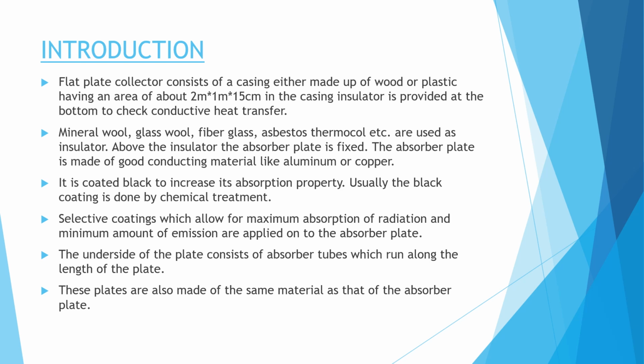Introduction. Flat plate collector consists of a casing either made of wood or plastic having an area of about 2 m into 1 m into 15 centimeter. In the casing, insulator is provided at the bottom to check conductive heat transfer. Mineral wool, glass wool, fiberglass, asbestos, thermocol, etc. are normally used as insulator.